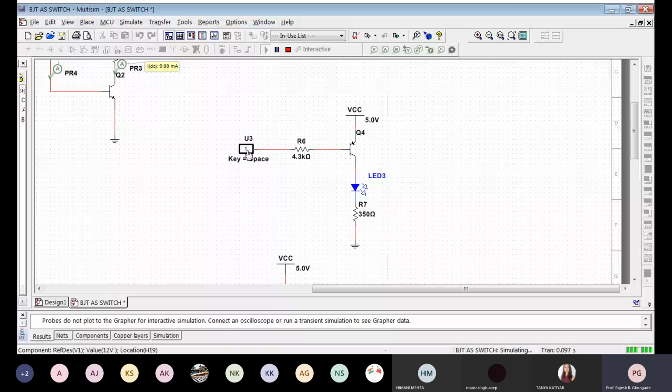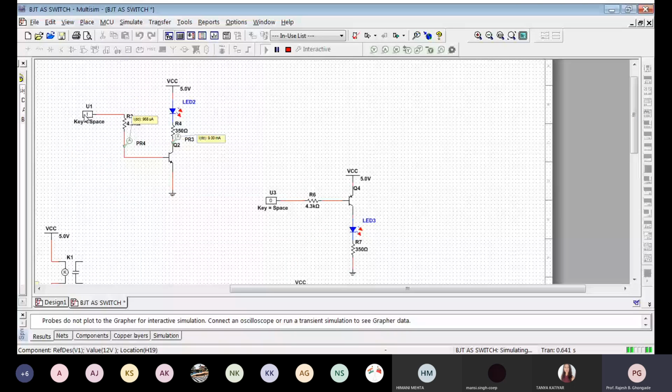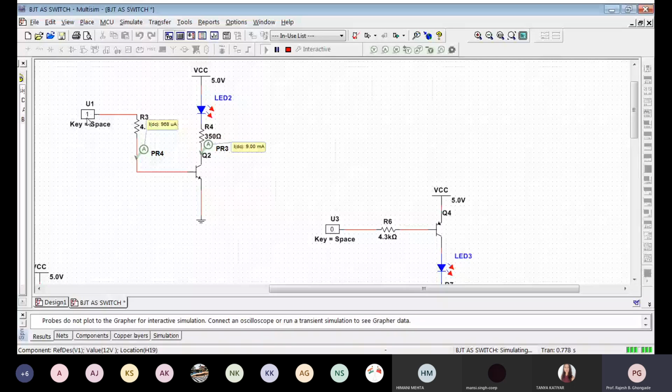now if I have a high, that is higher voltage, then the transistor is switched off, whereas if I go low here, the transistor is switched on. This is exactly the converse behavior of that of the NPN device. So you can see here that when it is high for NPN device, the device is on, whereas if this is low, and that is actually very easy to understand.